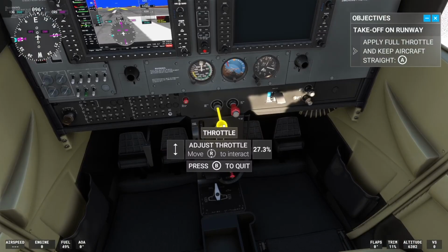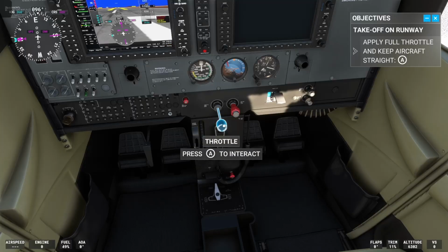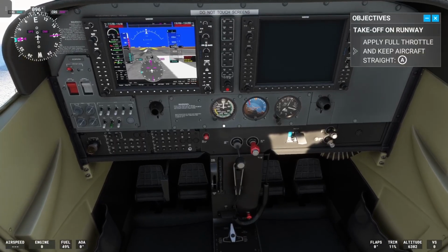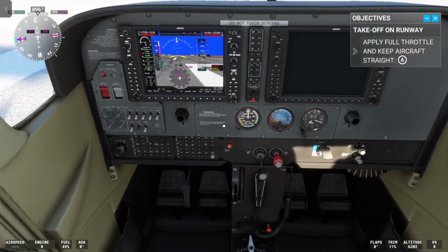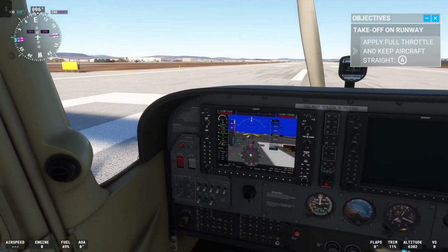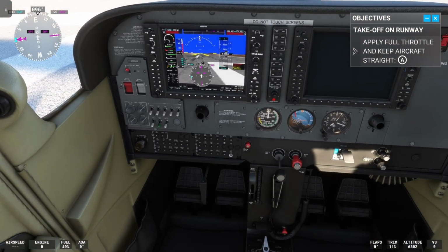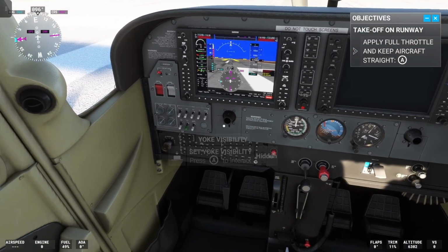What I've noticed here is that 1/4 is not 25%. Let's leave it open at around 37 something. There we are. Because the goal after ignition is reaching 1000 RPM. Around here, you'll see the numbers fluctuating. It should be close to 1000 in theory. So we are primed. Throttle's open at 1/4. That is check.